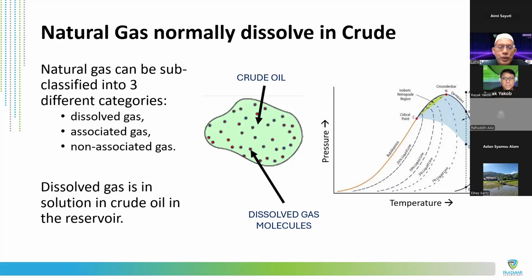In terms of the gas itself, as with crude, it is affected by the high temperature and pressure. Based on the drawing here, you can see that this is the bubble point, meaning everything above here is gas and everything below here is liquid. In the middle here is 25% liquid, so it's 75% gas in this region.